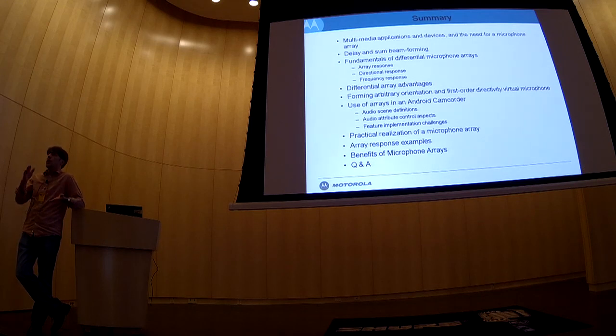Because theoretically, if there was no noise present, one can take this signal, which looks like a high pass filtered signal, and can equalize it all the way to DC. Practically, that cannot be done, because we will hit the noise floor and we will just increase the noise ad infinitum. It would be a very, very bad idea. So what we end up doing is a compromise where we try to get as low as we can go, closer to the full band signal, closer to the lower end.